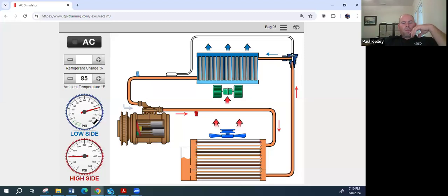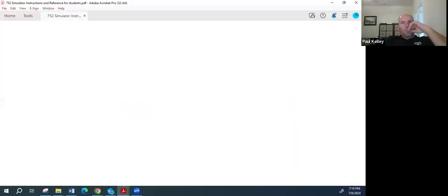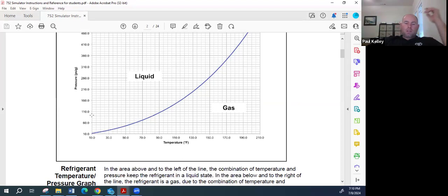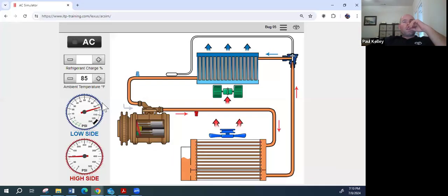Well, if you don't remember, I can help you recall. At 85, 70, 80, 85, running up to about here. Or about 60, 70, 80, 90. Yeah, about 90 something. Right? So it seems like probably the refrigerant is charged correctly.